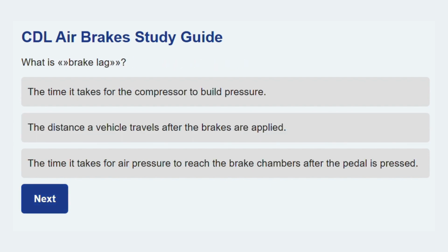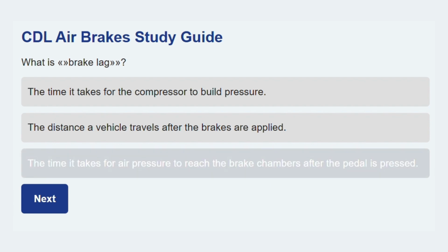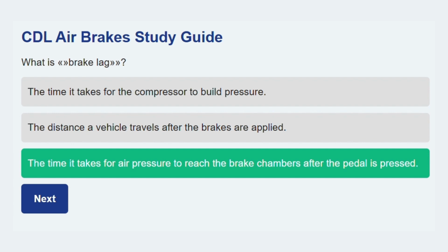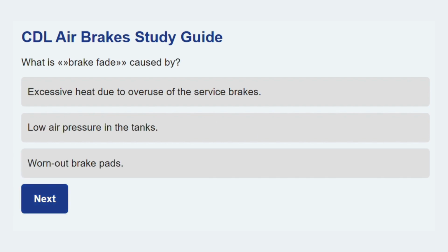Let's consider the next one. What is brake lag? The time it takes for air pressure to reach the brake chambers after the pedal is pressed. There's a slight delay from the moment you press the pedal until the brakes actually begin to apply.